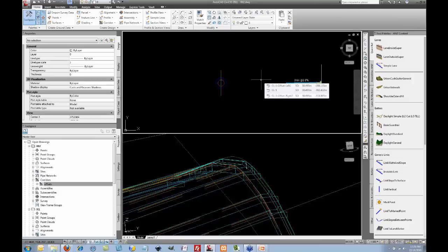So that's more or less the kind of bones behind the whole thing. You take that concept and you basically mirror it from left to right and add it to the two edges of your road, so your footpath and your edge of bitumen. So the only other thing that you would do is put on some design constraints just to show how you project grades and that kind of thing.